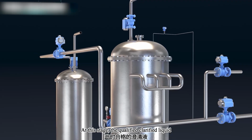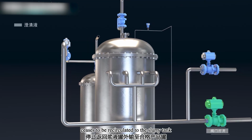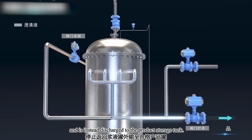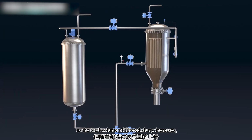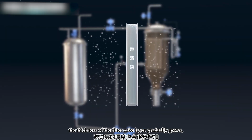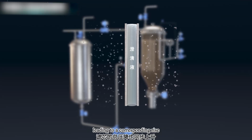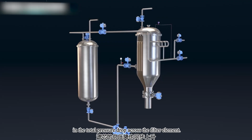At this stage, the qualified clarified liquid ceases to be recirculated to the slurry tank and is instead discharged to the product storage tank. However, as the total volume of filtered slurry increases, the thickness of the filter cake layer gradually grows, leading to a corresponding rise in the total pressure drop across the filter element.